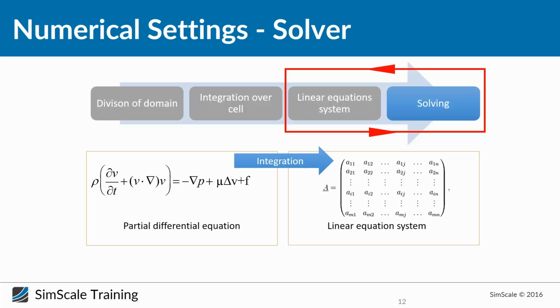We have some additional question. Josef wants to know that on page 9 of my presentation I'm not interested in the temperature field as well. Josef, you seem to be a very good observer. Yes, basically you also can add temperature field, just depends on your definition. For simplifying things, and because temperature field is nothing so important to understand the fundamentals, I decided to make all examples based on so-called cold flow, where we assume that temperature has no influence. But basically, if you say you have a hot flow, where density can change and temperature can change, you would also have to add an energy equation. Okay.